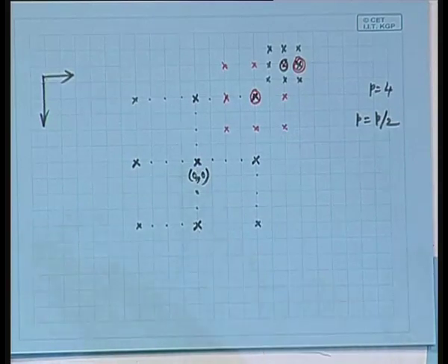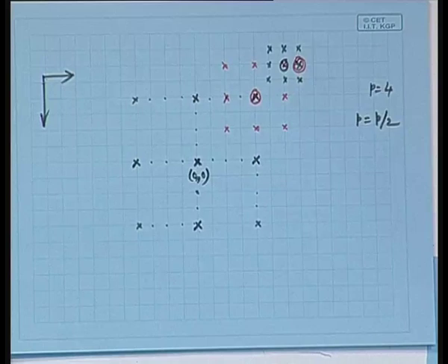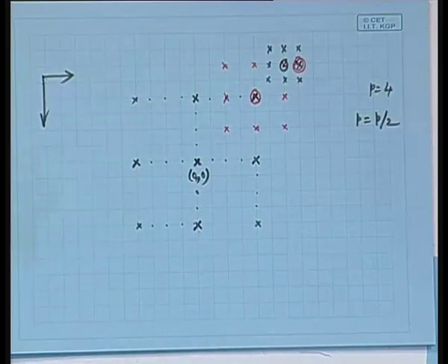Now, in the example I took p is equal to 4, and that leads to a search space of 2p plus 1, that is to say 9 by 9. Reasonably okay search position. And in this case, the number of steps that you perform is clearly 3. Of course, the people who originally proposed this algorithm had named it a 3-step search, but if you think of it in a very general way, you need not call it